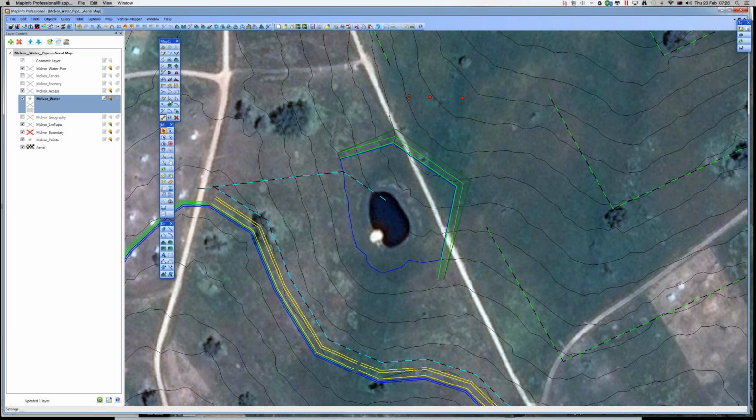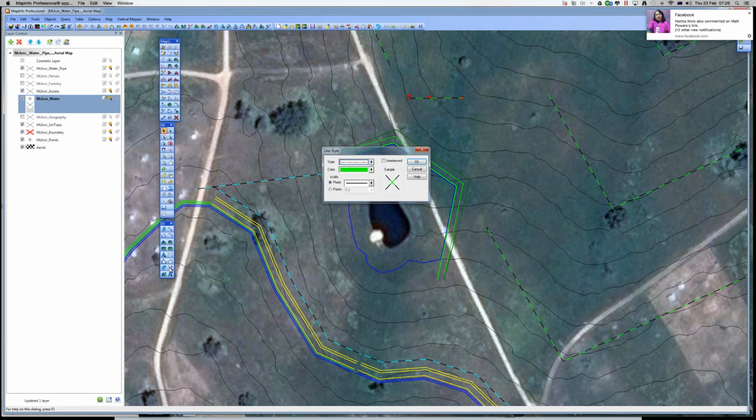Now, what you can do is just get a line and draw a line between, use the snap tool, which will come up down here, just click there, I'll just use the S key, and that snaps to a node. Right, if you turn it off, it's there. So we just do that and we go back to there. So you can say that that's the bottom of the axis, if you like. And I'll just change that line style.